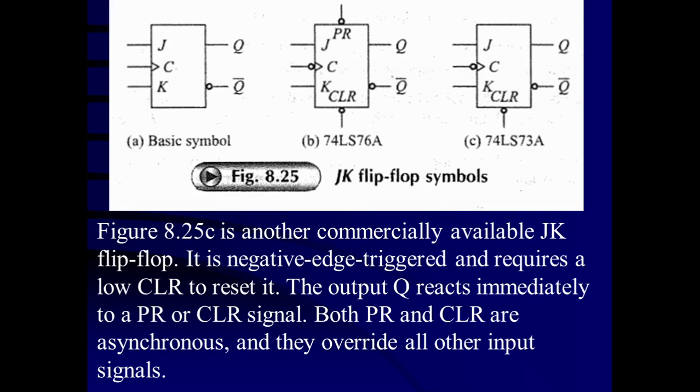In that case, what happens? A positive pulse forming circuit or negative pulse forming circuit is introduced at the input of its clock pulse. And it can be a positive edge triggered JK flip-flop or a negative edge triggered JK flip-flop. But if it is a negative edge triggered JK flip-flop, an inverter inside the IC has to be there. So the AND gate will respond on the complemented negative edge of the clock pulses.